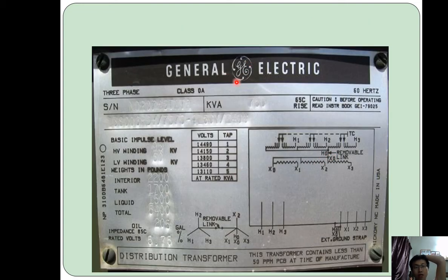Same as well, General Electric 750 kVA, and the details. And then this is YY connection. So high voltage Y, low voltage also Y. So we can tap in between. Then there's a common node, for the neutral wire is connected to the common point of the secondary side.